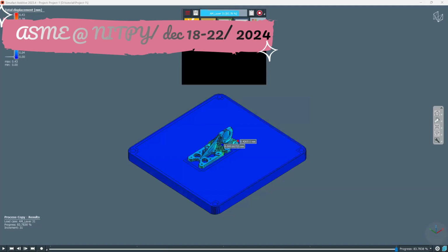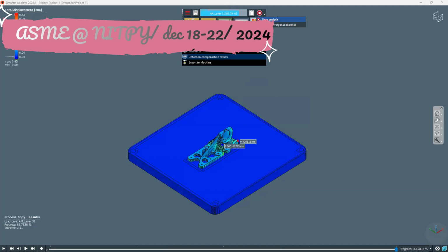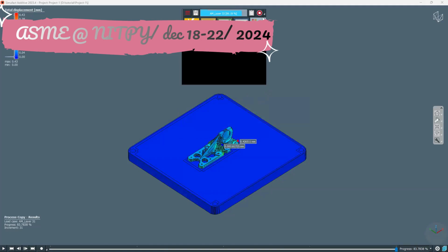Now I'll just kill this run. To stop the analysis in between, if you click on one process, on the top you will see a circle with a white square in the middle. This will stop the analysis and kill the runtime. Once the analysis stops, the bar will be orange in color, saying that only a portion of the result is available, not the full result.